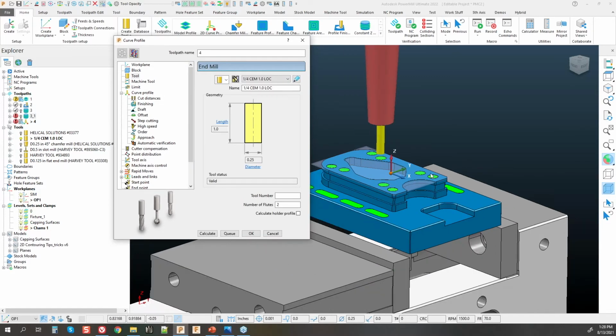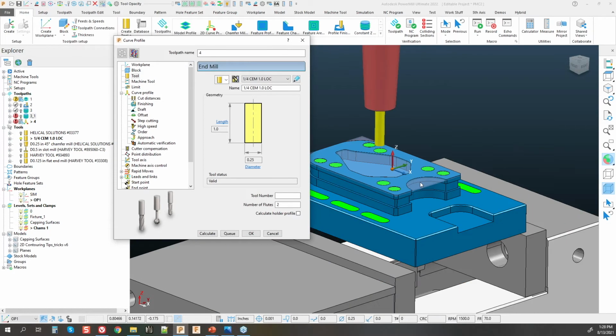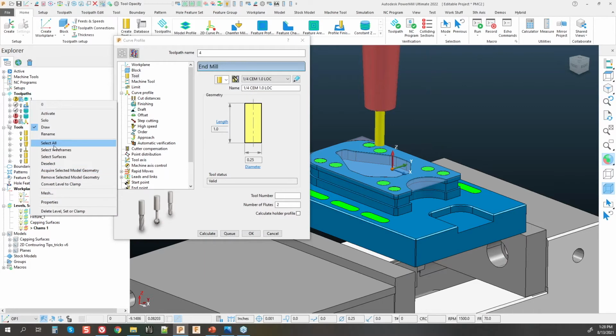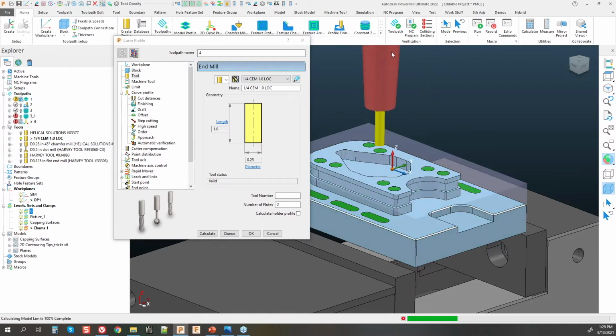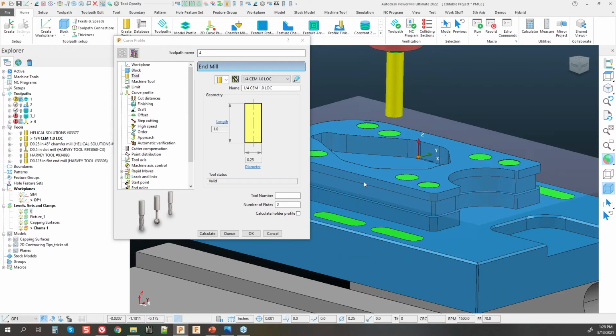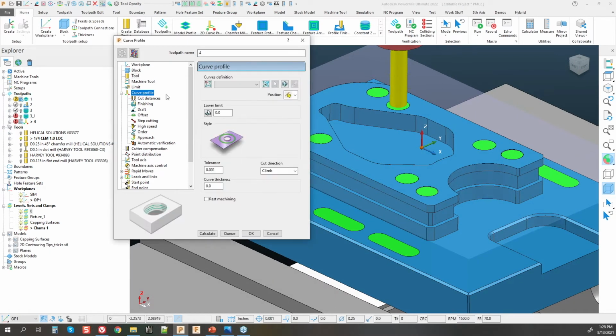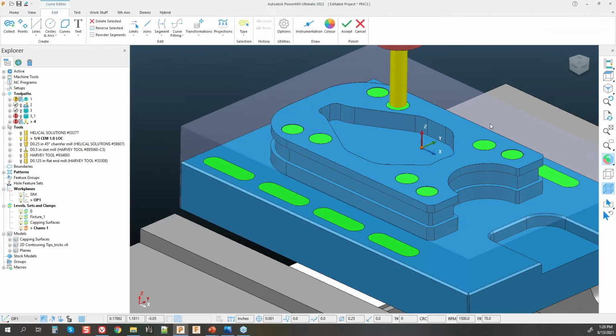Get back to our 1/4 inch end mill here. I will grab my part and just contour or create a block around my entire part. Just my block there. Now, in the pattern of this toolpath, once I go ahead and create a pattern, I will go right into my editing of the pattern.